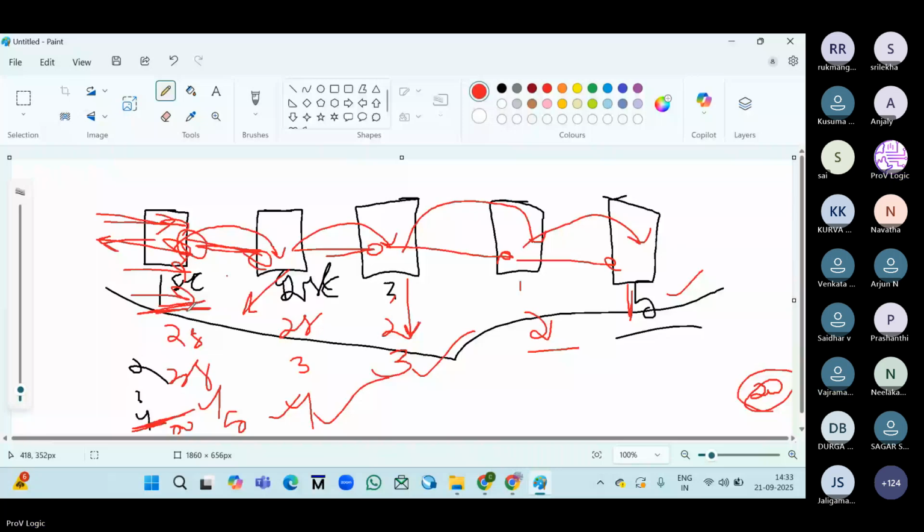Yeah, here also we are doing the same clock cycles. What it means, small shorter clock cycle, it doesn't mean like that. Whatever it is, it's a clock, that's it. We need to follow the stages because one output is dependent on another stage. Even here, whatever the write back, R1, suppose we are getting the output. The next instruction is dependent on this output. That's why we need to wait until we get R1. Did you get my point?